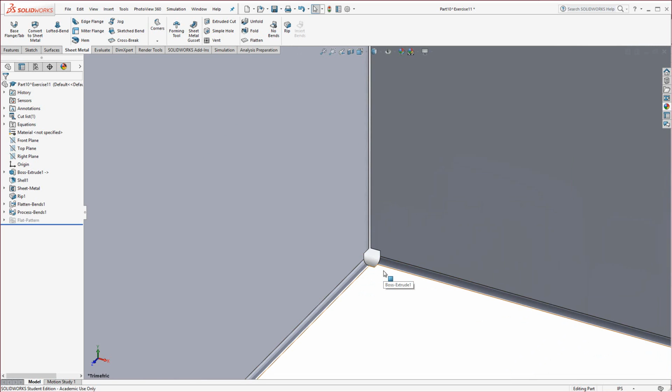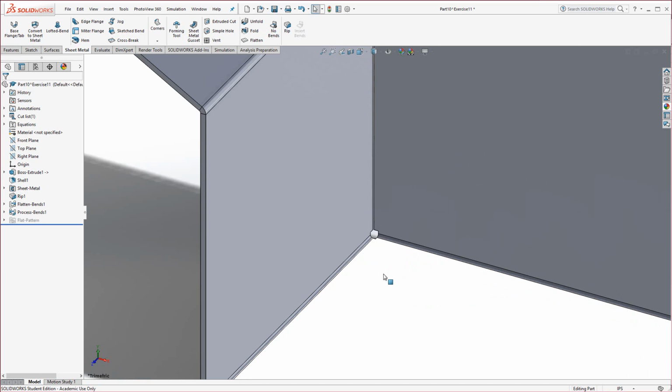The reason the relief cuts are there, if you're not familiar with sheet metal, is essentially if you've ever wrapped a Christmas gift or a gift to someone for a holiday or whatever it might be. When you wrap those corners, you'll see that they bend and they kind of get these like little ripples in the corners. Same thing can happen with sheet metal, and so you put a little cut in the corner and that prevents that from happening to some degree.